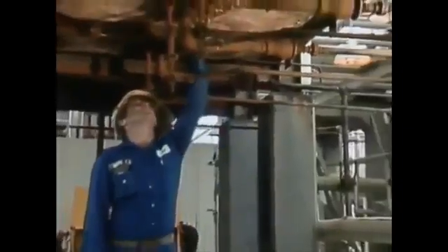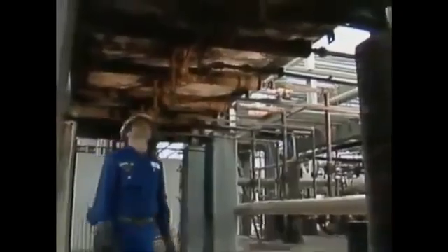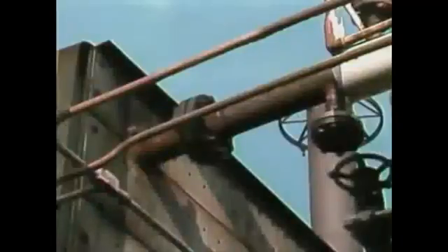An experienced operator can tell a lot about how a furnace is running by simply looking and listening. During your inspection, it's a good idea to check places where air may leak into the furnace. Air leaks can reduce the efficiency of the furnace and give misleading draft and excess air readings.